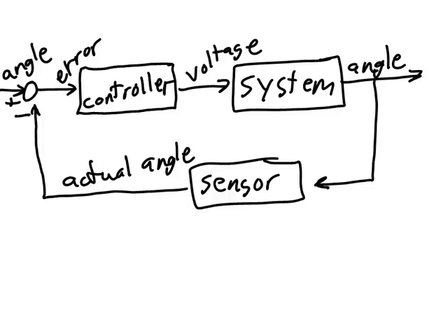We program the microcontroller with a variable that says what angle we want the pendulum to be at. Then we connect up the sensor to the microcontroller. The microcontroller reads the sensor, subtracts the sensor value from the angle we want the pendulum to be at. Then it calculates the voltage to the car and produces the voltage with something like a PWM pin.